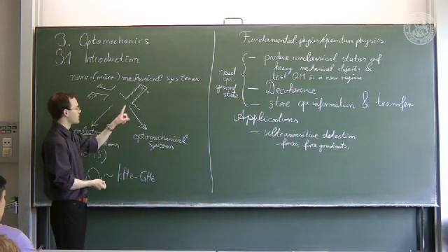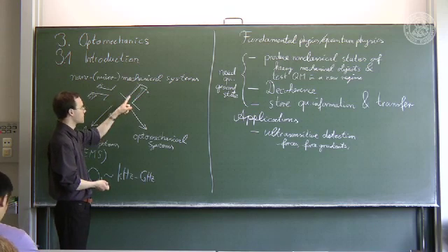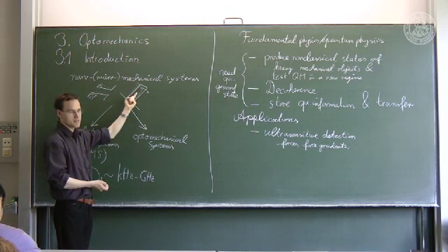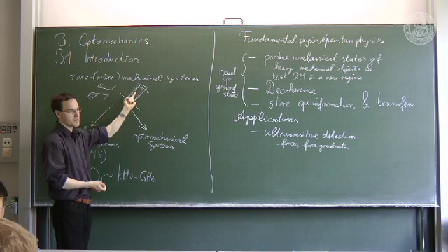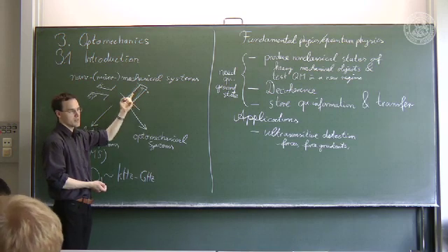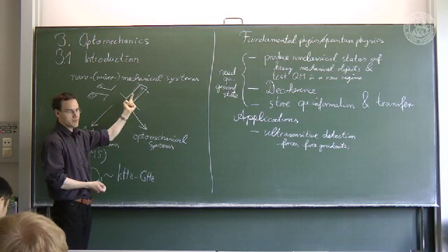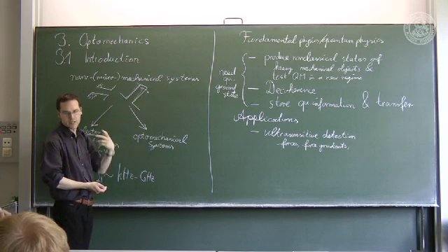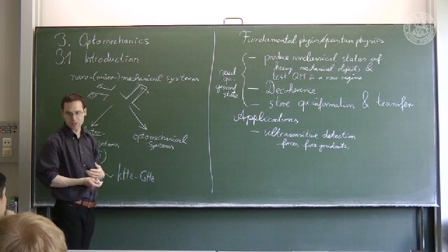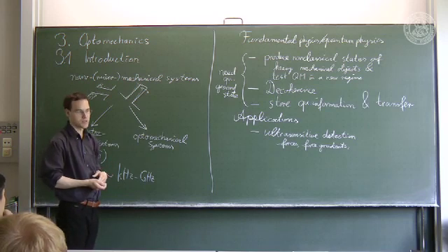Something else that you can detect in these systems is simply changes of mass. Imagine you have this cantilever, it has a given fixed spring constant, and now there's a slight change of mass. Evidently this again changes the resonance frequency, and that you can detect with very high precision.